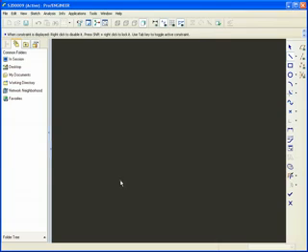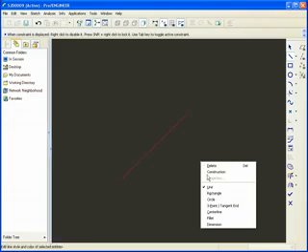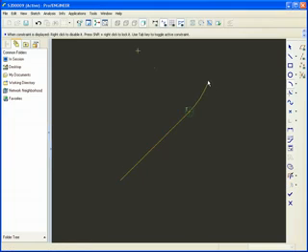Now if I make a straight line, that would be a constant pitch. The slope would be the pitch. The number of turns would be determined by that slope. If I want it to vary, all I need to do is change how this line behaves. I might want to make a couple of arcs on it, something along those lines. Let's make these two radiuses equal to each other.